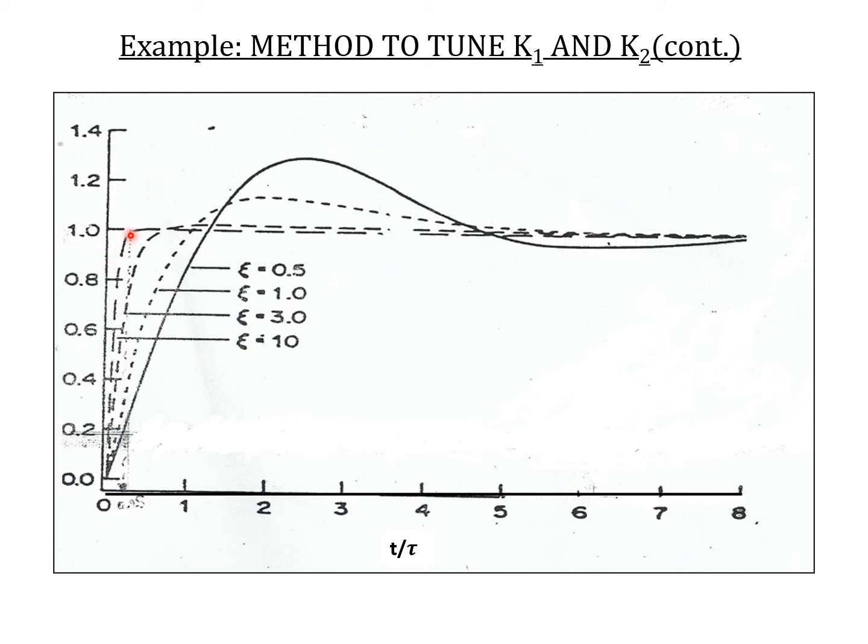So from there, we said that the time that we want is 20 minutes, so we equate that to 20 minutes, and we get out K1 and K2 as I've shown you previously. From there we basically get these tuning parameters that are used for the GMC method. As I said before, it's nothing to do with the tuning that you normally use for P, PI, PID, but it's related to the K1 and K2 formulation that we use for the GMC method.